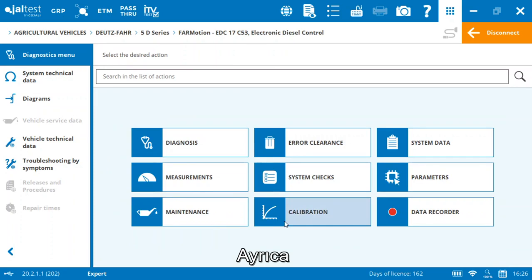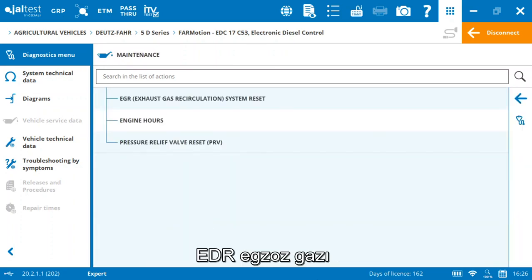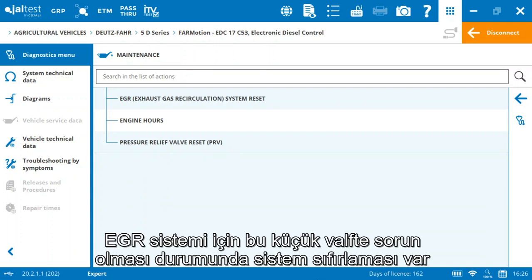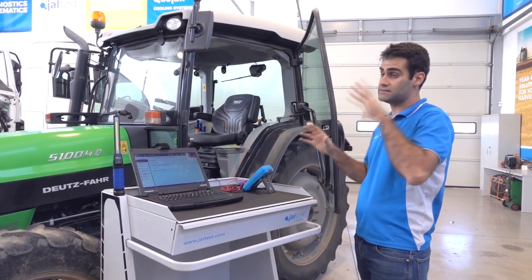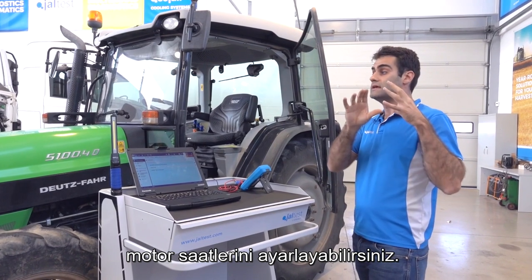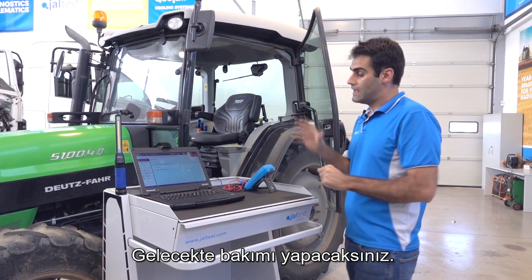Also very nice to take into account in this diagnostic menu, maintenance. We've got the EGR exhaust gas recirculation system reset, just in case we've got some problems with this small valve for the EGR system. Engine hours, which is for the maintenance. You can set the engine hours at which you will do the maintenance in the future.